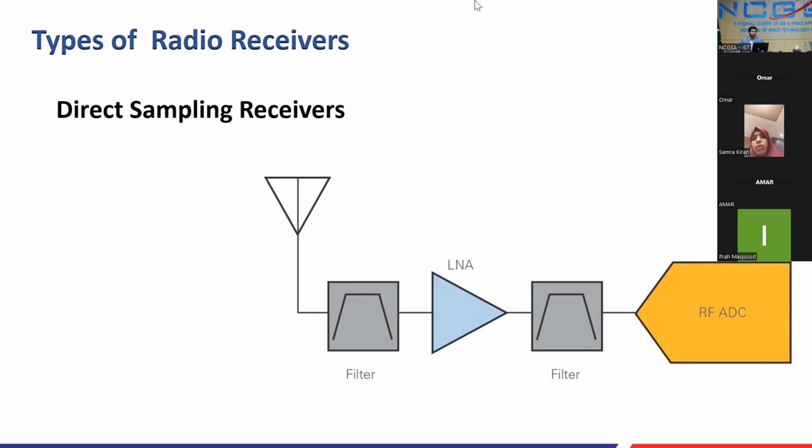For example, if you are asking about a direct sampling receiver, digital receivers can implement sharp roll-offs. In traditional receiver implementation, you have issues. Like in the super heterodyne receiver, which I explained in the previous slides, especially in heterodyne architecture where you have a single mixer, there is a problem when you move more towards DC. You need high roll-off filters that are difficult to fabricate unless you have a high order cavity filter. They do have better Q factors, or dielectric resonator filters. So that is a trade-off, because if you are working at 500 or 600 megahertz, a filter of that size will be very big.